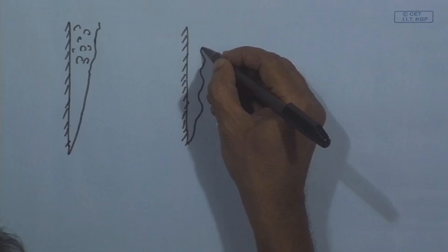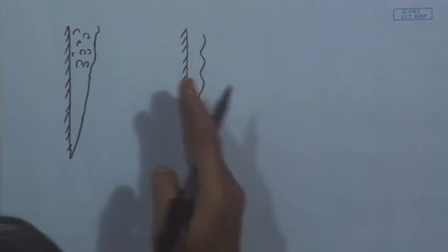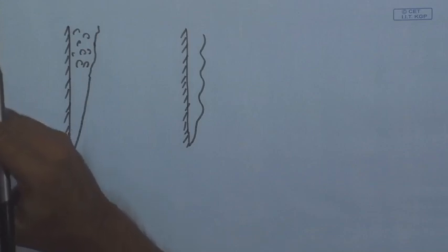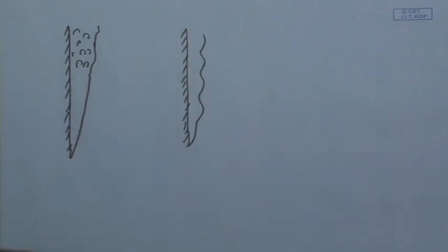As I have told, there is Kelvin-Helmholtz instability if there is relative motion between parallel layers of fluids, so due to that there will be undulations. These undulations will of course increase the heat transfer to some extent, but at the same time they make the analysis more complex. So, there are issues in film boiling which cannot be captured with the simplistic analysis which we have shown. There are issues like other complex geometries and the effect of fluid motion. So, this is just a beginning.